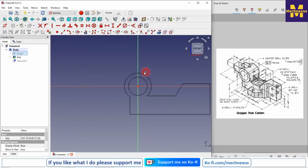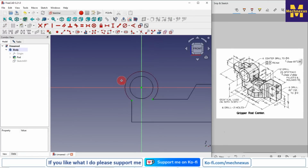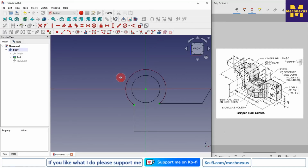And now I will project this outer arc. So I will click on the project external geometry and project it, and now I will use the polyline tool to create a rough profile and then we will constrain it.